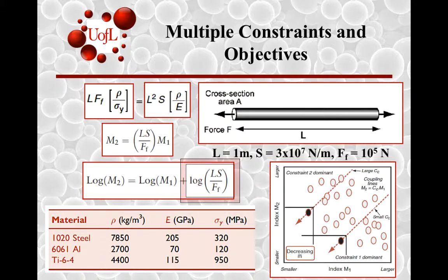So mainly what you have as a powerful representation of material index is that once you have represented different attributes of materials, which are represented by these dots, you will be able to take into account different loading conditions and different geometry conditions that are constrained within the design, and be able to choose different materials for different design variations from a single plot.